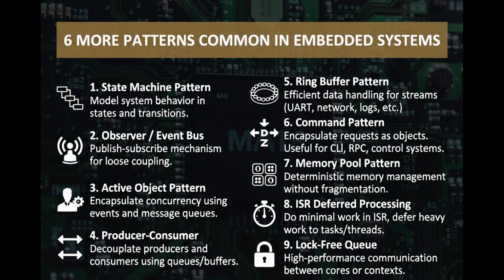Producer-consumer pattern decouples data production from consumption, used heavily in DMA pipelines, networking, audio systems, and storage controllers. Ring buffer pattern. Ring buffers provide efficient streaming data transport. Used in UART drivers, packet processing, logging systems, and audio pipelines. Memory pool pattern. Memory pools provide deterministic allocation without fragmentation, critical for RTOS kernels, packet buffers, and real-time systems.